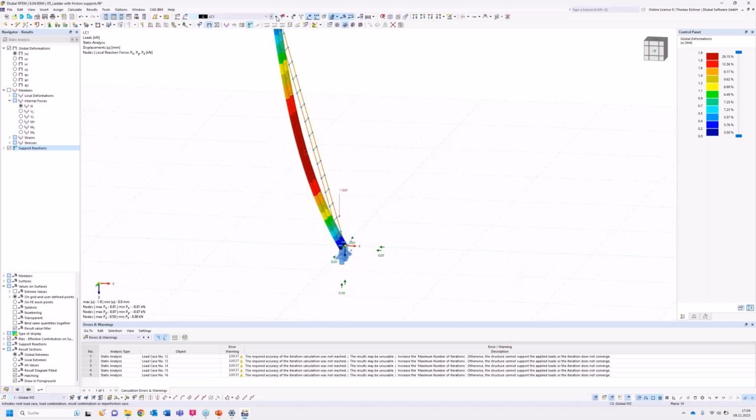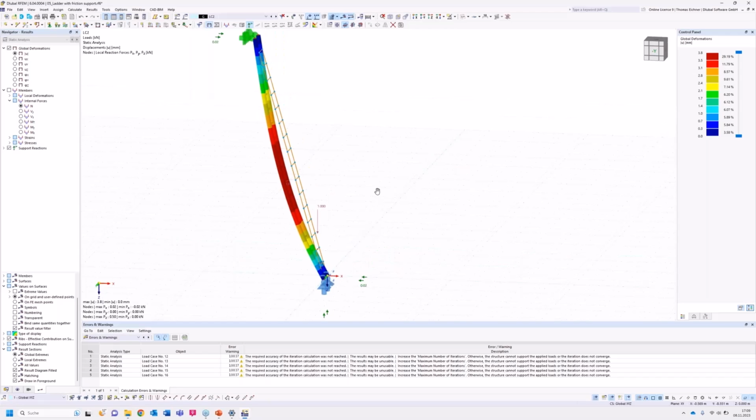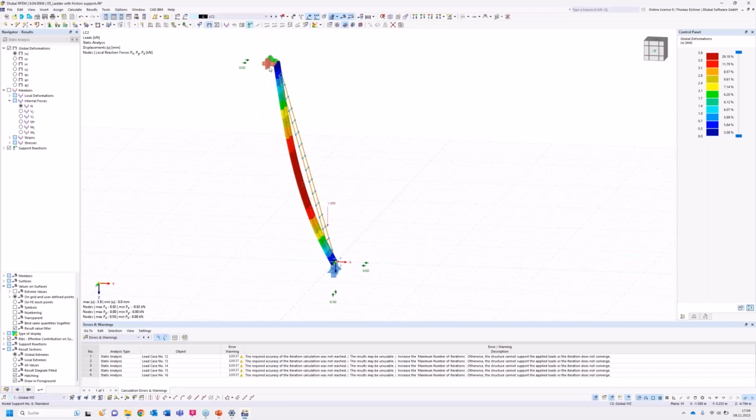But when we step up the ladder now, we can see this value rising. This results from the equilibrium of moments. We will go away from the start, and therefore the distance of this moment will be higher, and therefore this force will go higher. Way simplified. And we can step up the ladder and we will see this value going up.